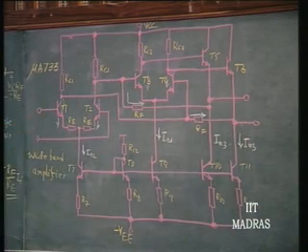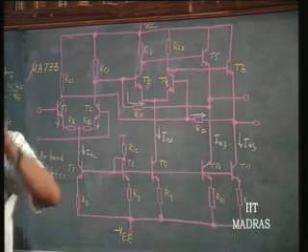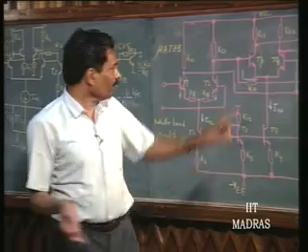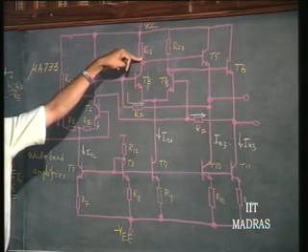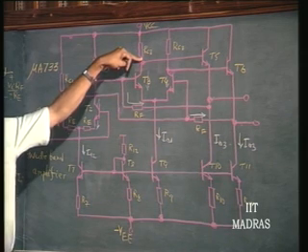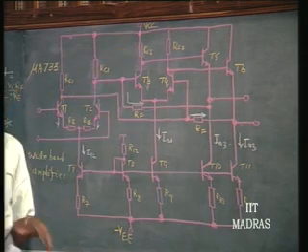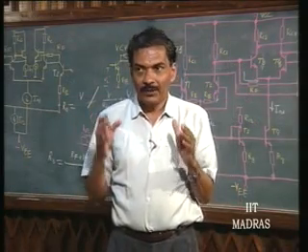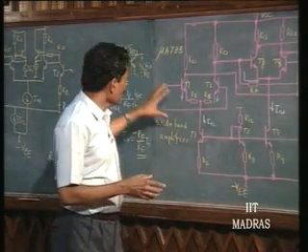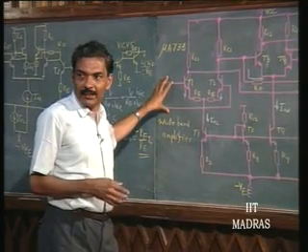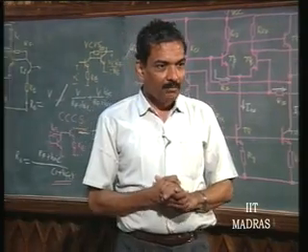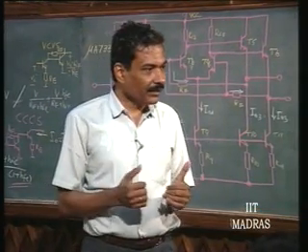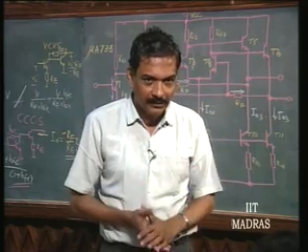So, please do this, and then you will know how much these amplifiers can handle as output signal, depending upon the bias voltage here. Their capability for handling signal is going to be determined. So, I would like you to come out with the voltage swing capability of the stage. That is, how much input swing it can handle, how much output swing it can handle as far as this wideband amplifier is concerned. Please determine that after determining the operating point of all the transistors.